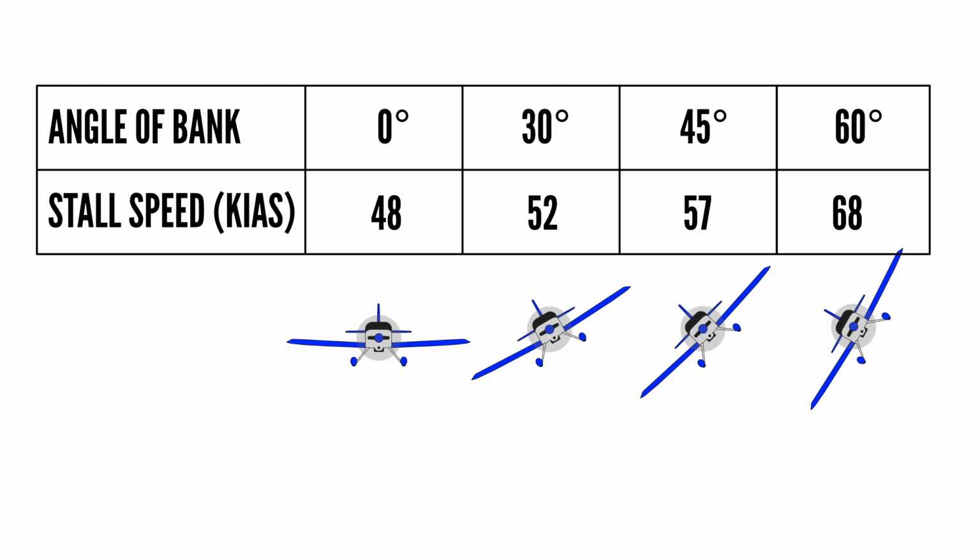I cringe whenever I see something like this. It wrongly suggests a direct link between bank angle and stall speed, which is simply not true. Worse, it distracts from the one and only thing that can stall an airplane. This association between bank angle and stall speed should be removed from pilot training entirely. Instead, the only thing we should mentally associate with a stall is the position of...